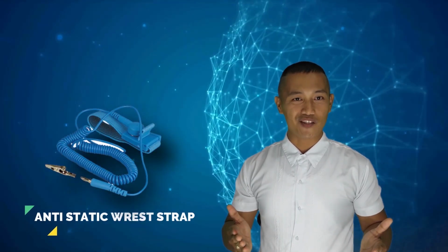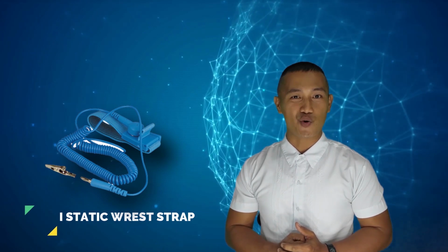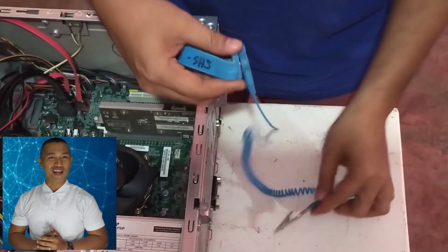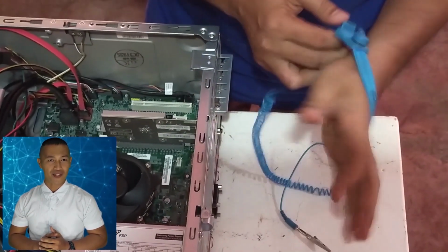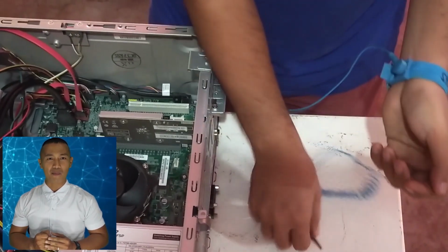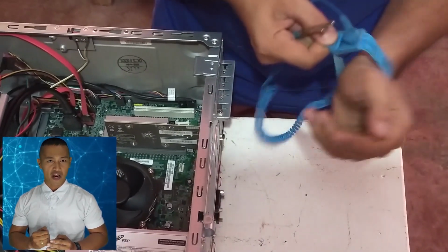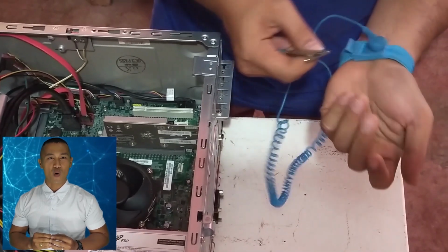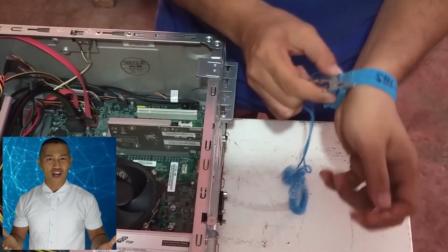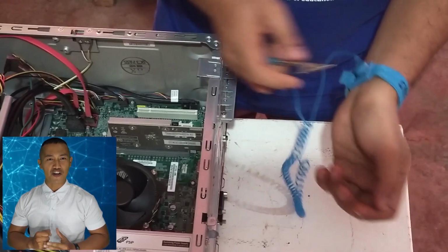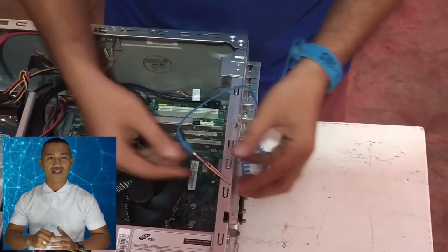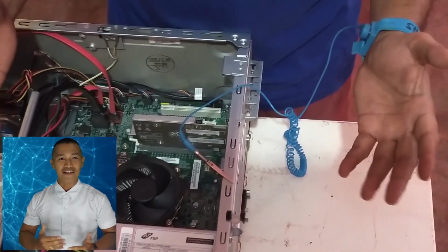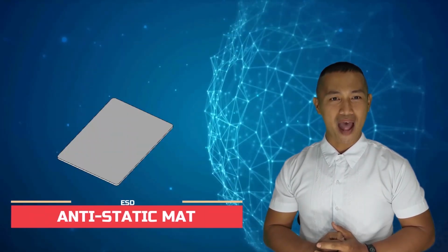Anti-static wrist strap is used to prevent ESD damage to computer equipment. You may use this by inserting your hand into the manhole of the anti-static wrist strap. Then clip the alligator clip on a power supply screw. Check that it is clipped firmly. Once everything is set right, you should have the assurance that you are grounded by holding any metal around you for 5 seconds.